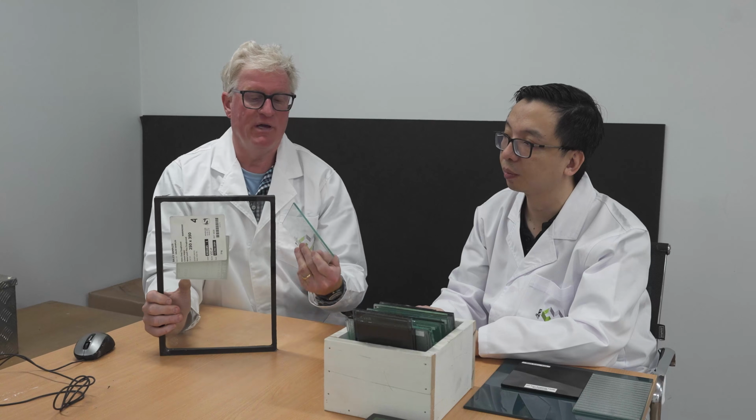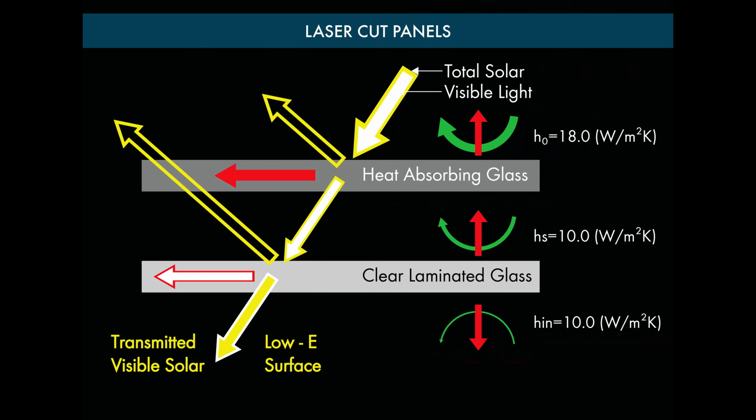One is a soft coat, a vapor deposition coat. That soft coat needs to be protected. And often a soft coat will be on one of the inside layers of a double insulated glass. The cavity facing. Yes, the cavity facing sides, right? With a soft coat, that's the case. I believe people like Pilkington and LOF, Libbey-Owens-Ford, they made a very tough low E film or deposition coating onto the glass. And that coating was quite durable, and that could be exposed on the inside surface as well of the glass. The coatings, yes, they can vary.